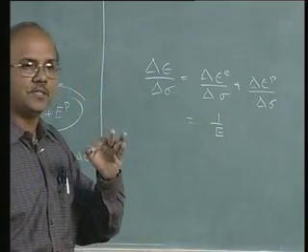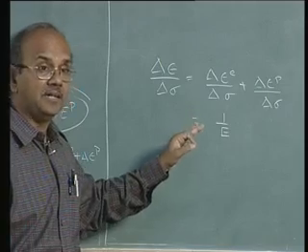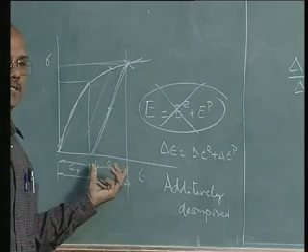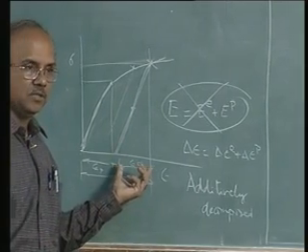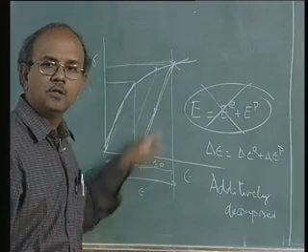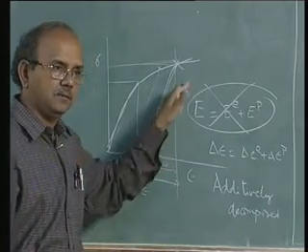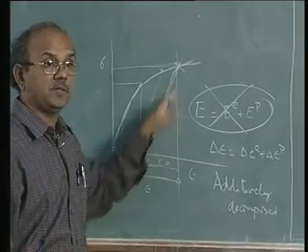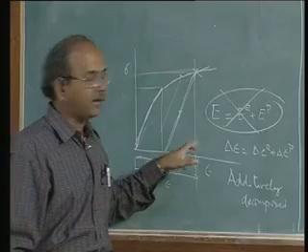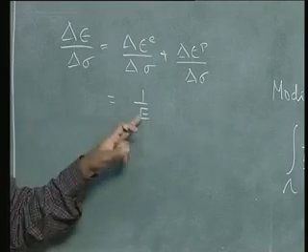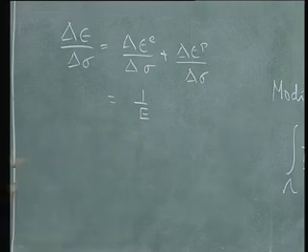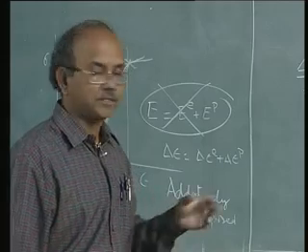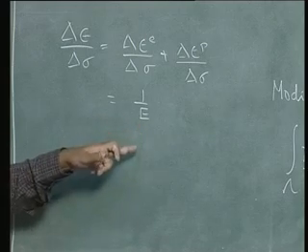So the first thing that you have to notice is that E values are still valid. Obviously from this graph you will see this is epsilon E, so you can consider this as delta epsilon E. Because I am going to unload through the elastic path, the relationship between sigma and epsilon E, even in the plastic region, is through E, capital E. Please note again the difference: this is my Young's modulus, not my strain. There are going to be slight confusions on this, but the context will tell you what we mean. This is not my finite strain. This is my Young's modulus.